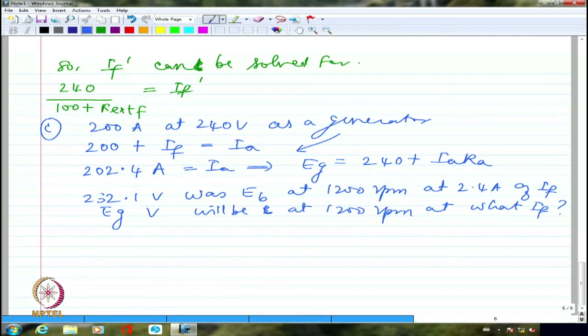Most of them work on ratio and proportions because we hardly ever give the nonlinear portion of the magnetization characteristics very often. We try to confine ourselves as much as possible to the linear portion, but if we are going into the nonlinear portion, we may say, although the increase in the current is by so much, armature reaction weakens the flux by so much percentage. That's what we say.